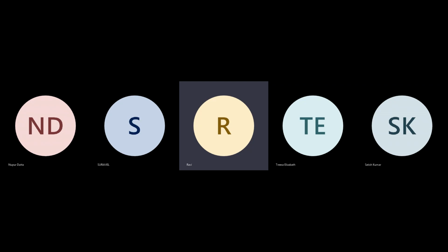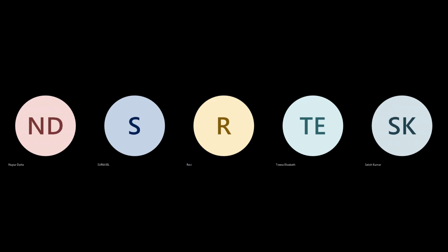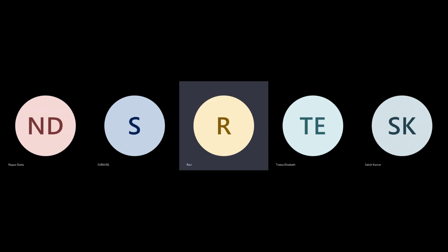that means you have to make scenarios also, right? Yes, you have to do scenarios. Okay, you have to keep at least, if you are having multi-mode, multi-corner, right? Like don't run placement in 20 corners. No. As I said, mission critical. 2, 3 corners. That's what you should keep simple. Especially initial trials, you have to keep it very, very simple. Maybe just focus on PVT for that.